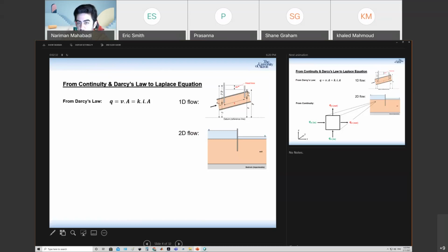Although actually the direction of my pipe is from a lower depth to a higher depth. So you may say that we're going to have a flow from the right side to the left side, right? But it's not just like that. It's not just about the gravity. It's about the energy of water, or the total head of water.